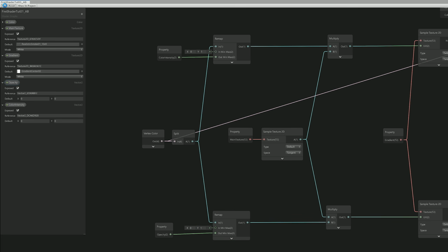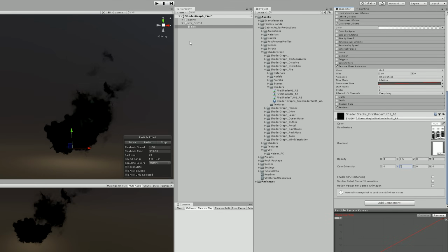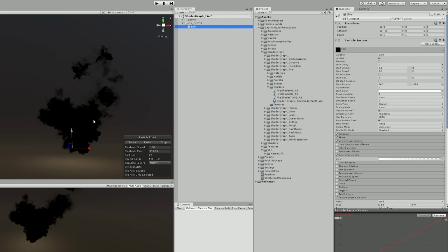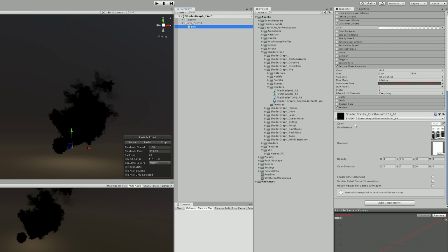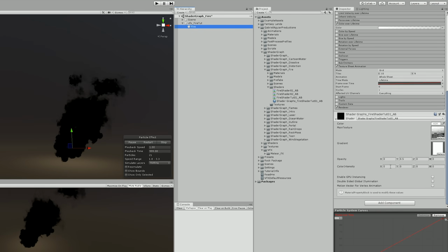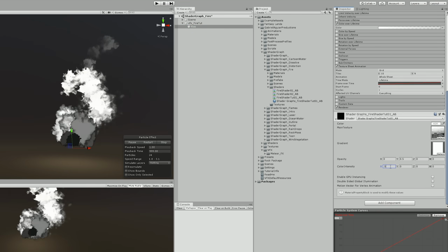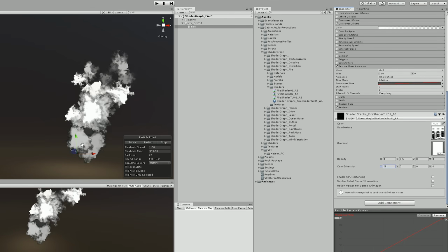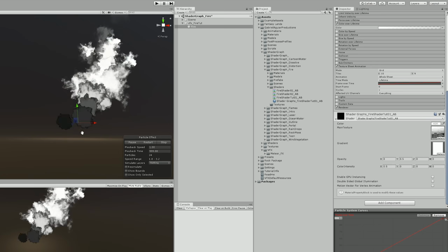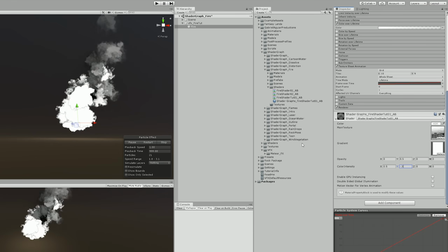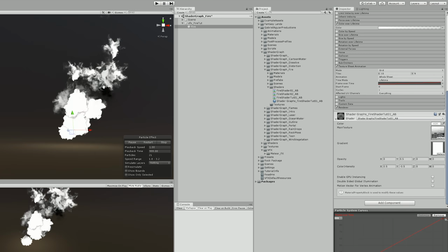Now back to Unity. Everything is looking black, and that's because we are remapping the minimum and the maximum of the vertex alpha to be 0 in the color intensity. We need to open up this range, and if we insert a minimum of 0.5 in the X, we have the opposite of what we want. We have black at the bottom and white at the end, but if we insert minus 0.5 in the Y, we are basically inverting the colors, let's put it that way.